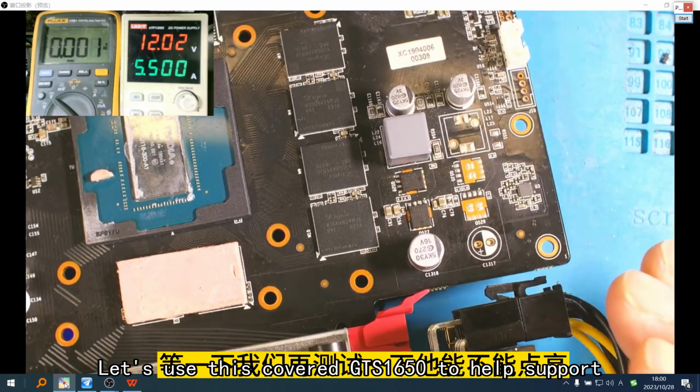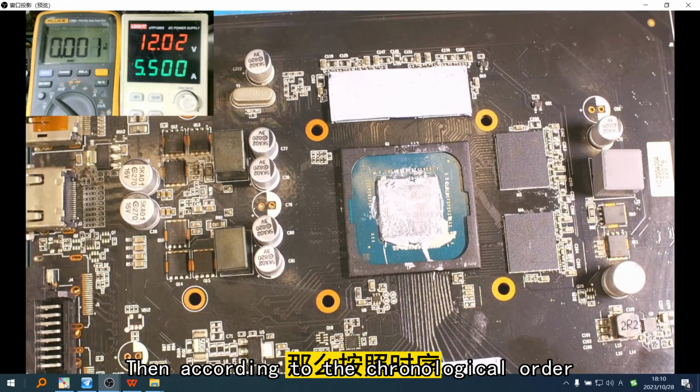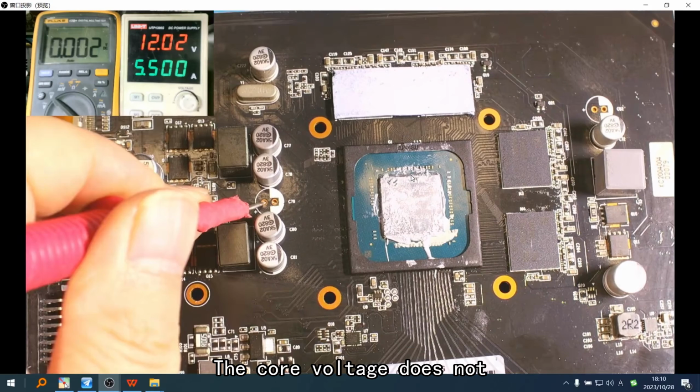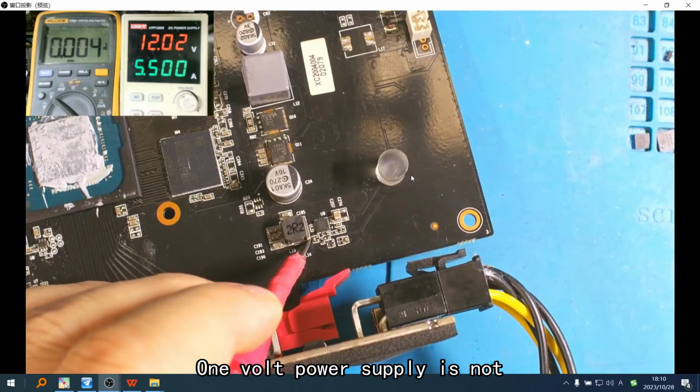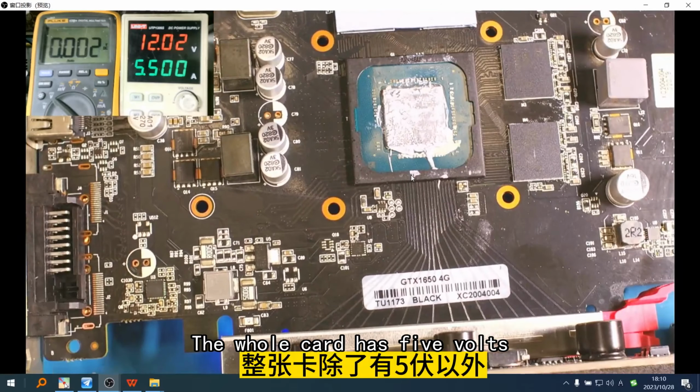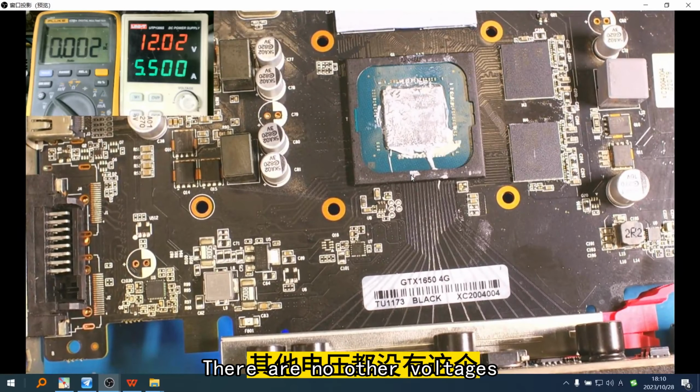Let's use this 1650 to help. I checked the appearance and the resistance values for this card. They're all normal. Let's take a look at the voltage. 5V is normal, but 1.8V is not. Then, according to the timing sequence, all the voltages behind it will not be generated. The core voltage is not there, the 1V power supply is not there, and there is no video memory power supply. The whole card has 5 volts, and there are no other voltages.